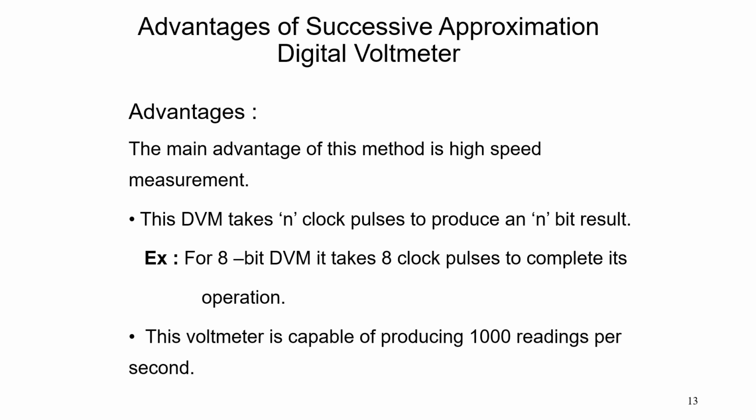If the total reference voltage exceeds the unknown voltage, the comparator produces an output that causes the control register to reset its second MSB. The converter output then returns to its previous value of half volt and awaits another input from the SAR.